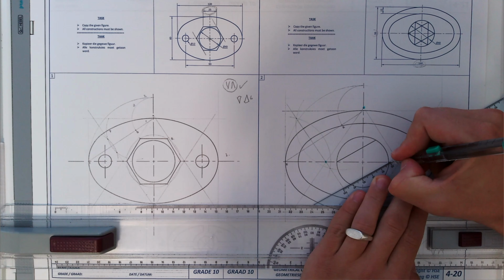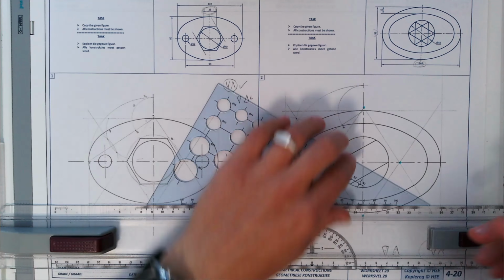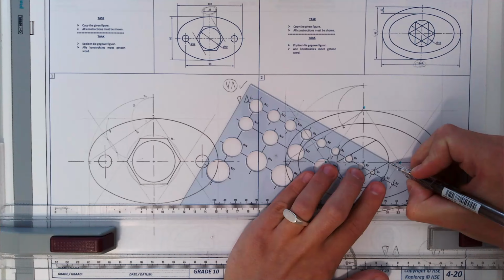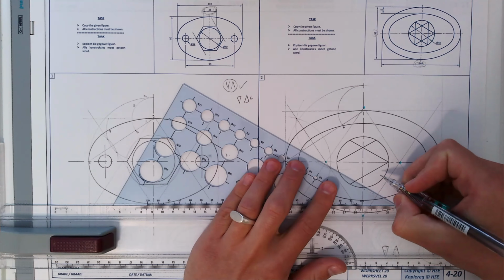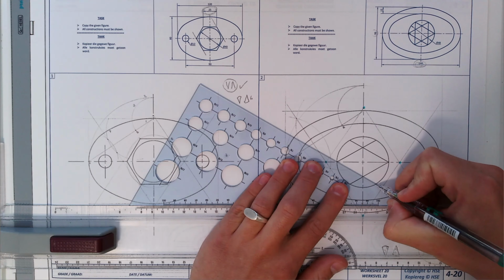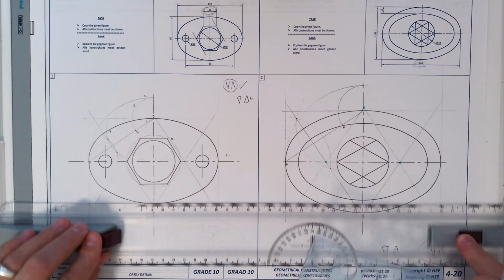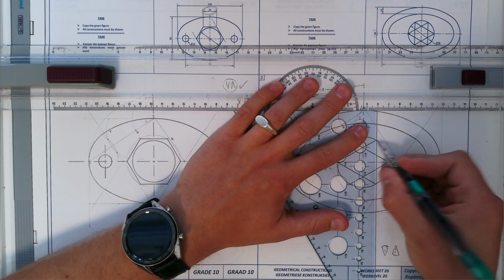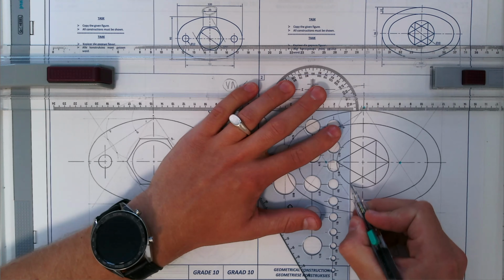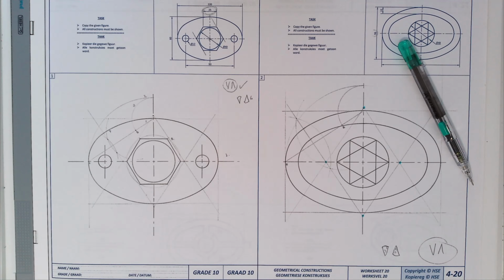Center point, all the way until you touch the arc of the circle. Then this side, the opposite direction, 30 degrees, and there 30 degrees, and then you can just close it on these two sides, over there and over there. And that is how you do the drawing on the right on page 4-20.